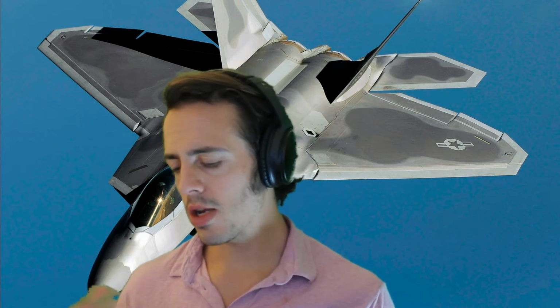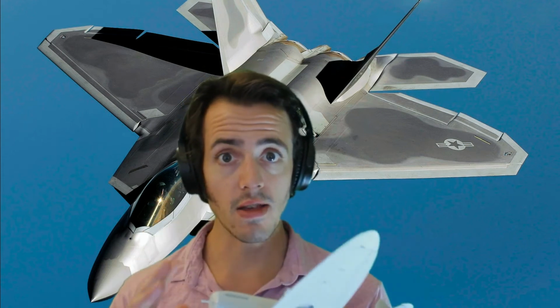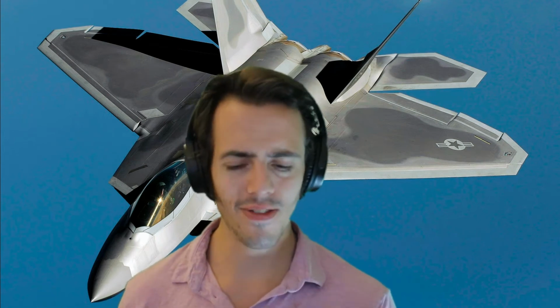So we introduced this and we looked at them a little bit to understand the relationship between these derivatives and aircraft motion. Some of these are really easy to think about in terms of their first order behavior. So the pitch stiffness, i.e. CM alpha, is the tendency of the aircraft to return to a level pitch attitude if disturbed. We also thought about some of the cross couplings. The tendency of the aircraft to roll when it yaws is given by the derivative CLR.